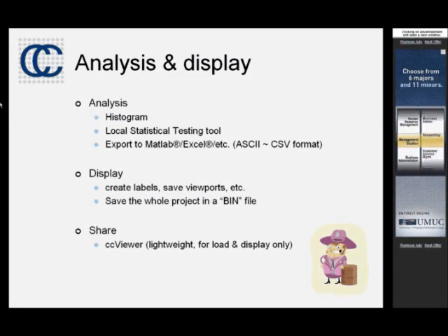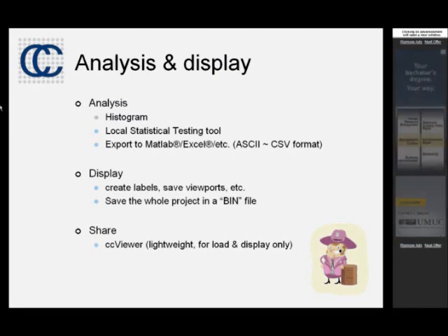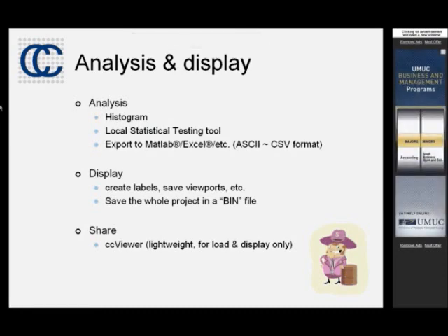There's a quite tricky tool named local statistical testing, which is a bit hard to tame, but which lets you, if you know quite accurately the noise of your measuring process, and you really need to achieve a very good accuracy on the distance computation results, try to classify the points between those that have non-zero distances but in fact only correspond to noise, and the points that really correspond to differences.